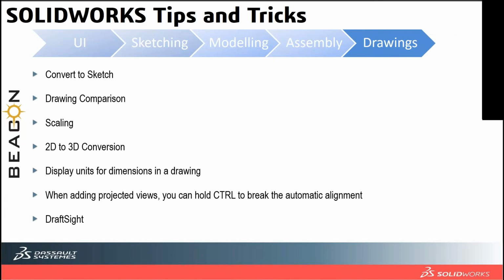Then you just go inside drawings, evaluate. You have something called compare documents. You can select that and start comparing your drawings. Sheet scaling: you need not right click properties, sheet scaling. It's right there in the tab below.